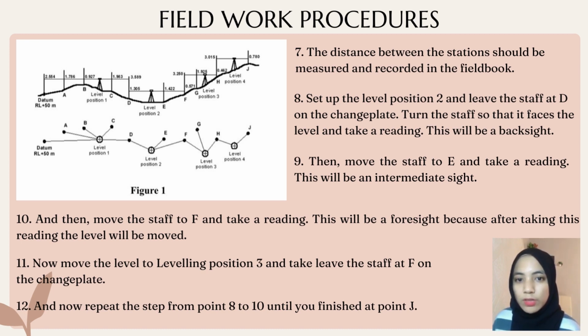Now, move the level to leveling position 3 and leave the staff at F on the change plate. And now repeat the steps from 8 to 10 until you finish at point J.